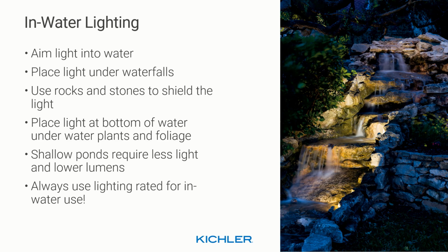In-water lighting can immediately elevate a water feature at night. The constant movement is magnified by the light. Remember, shield the light as needed. Remember to aim the light inward at or under the water and not toward the shoreline. Placement underwater plants can also be interesting. Always use in-water rated lighting for these ponds, streams, and waterfalls.